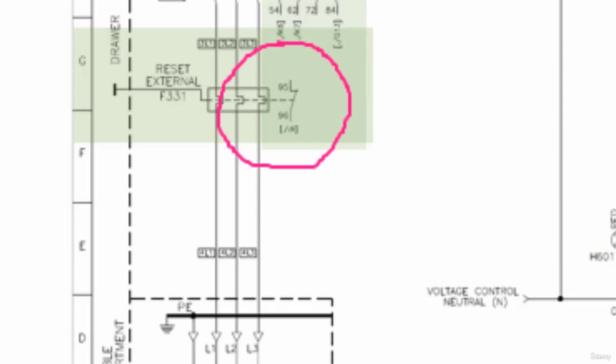Okay. Now, the address here would be, let me write it down, 0 slash J9. Okay? Now, this 0 here, guys, means that this whole closed contact, the exact same equipment, has actually been used in another sheet somewhere else. All right? And, well, the J9 here actually stands for the exact address of this equipment.